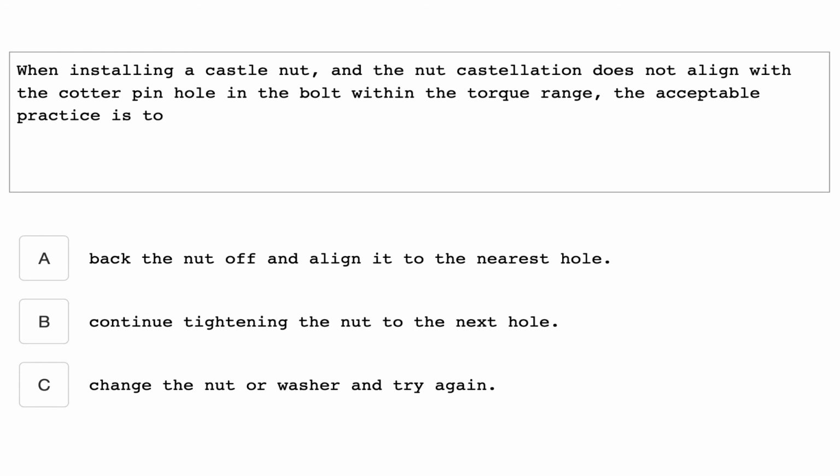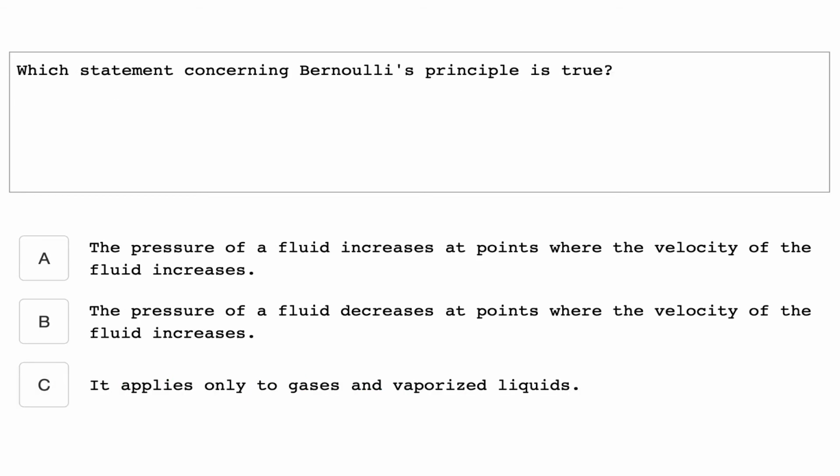When installing a castle nut and the nut castellation does not align with the cotter pin hole in the bolt within the torque range, the acceptable practice is to change the nut or washer and try again. Which statement concerning Bernoulli's principle is true? The pressure of a fluid decreases at points where the velocity of the fluid increases.